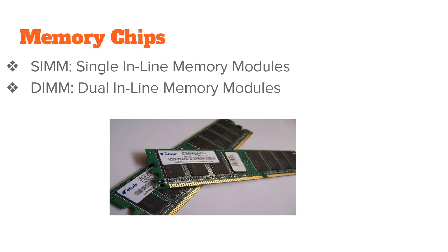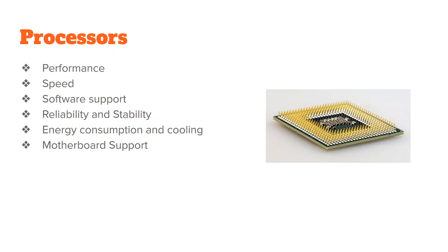The main difference of the two is that opposing pins on either side of the board are tied together to form one electrical contact in a SIMM, whereas in a DIMM, the pins are electrically isolated to form two separate contacts. And DIMMs are often used in computer configurations that support 64 bits. So this is the difference between a SIMM and DIMM.